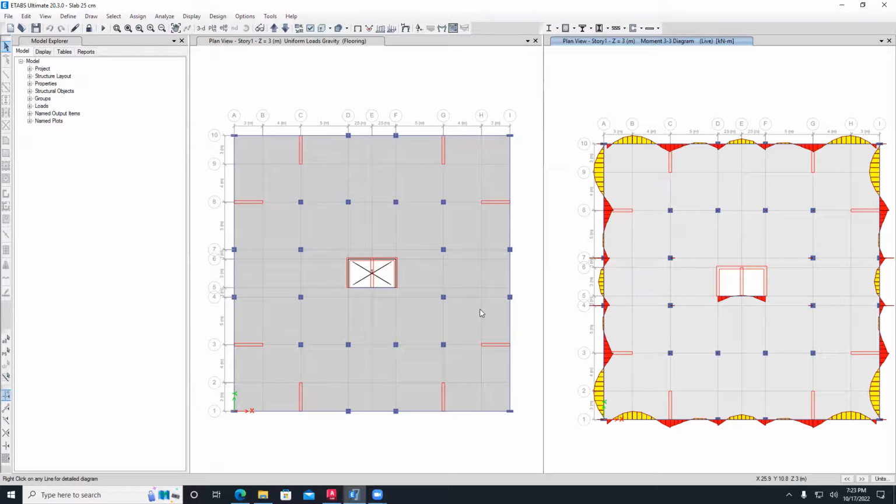When we do design, we add factors of safety and we add things that might not be logical from a structural analysis, but are logical from standards and safety. So this will be the actual moment, but we add some negative moment, just to be cautious that there's some negative moment that will be sustained. All right, so let's unlock this model or save this model as 3D.